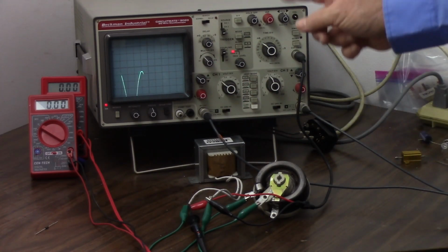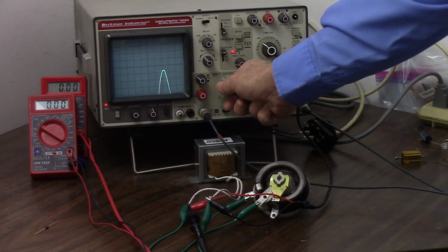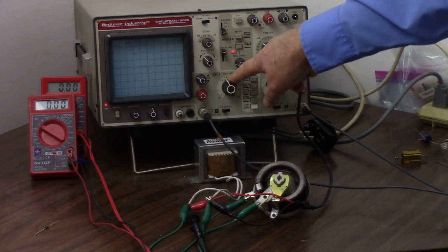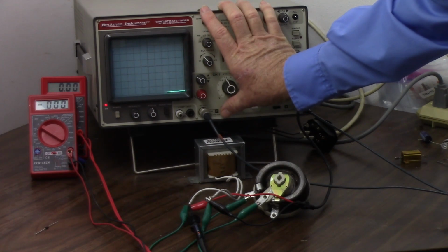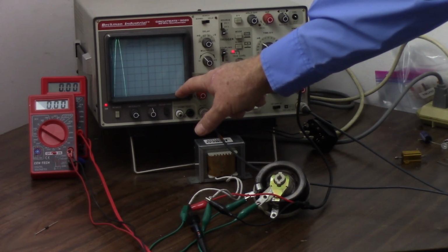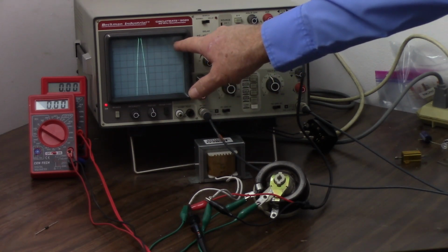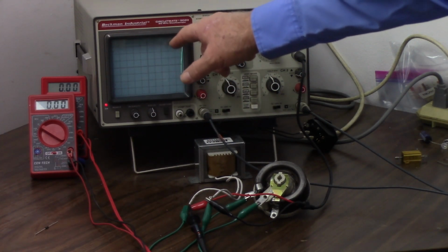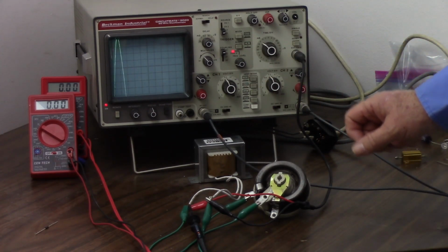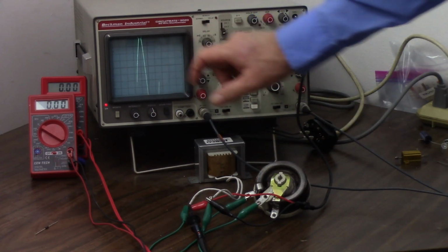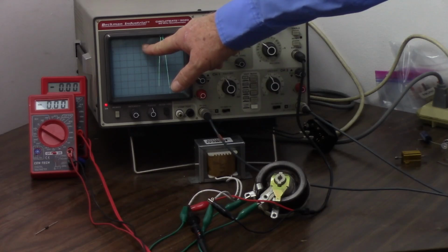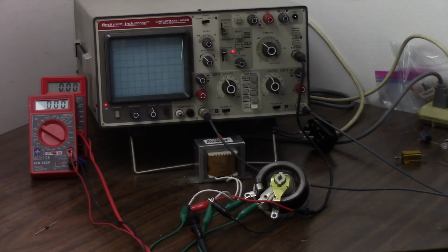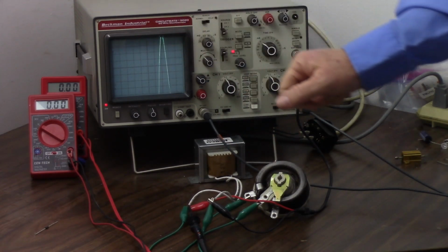Flip that up there, and I'm going to set this up at 0.2 volts per division times 10, so that's 2 volts per division. Let's double check our ground here. There we are. So 0 volts is at the bottom, so it's 2, 4, 6, 8, 10, 12, 14, 16 volts is kind of going a little bit off the scale to give us our 16 volts. So now what I need to do is start loading this down and watching that peak voltage. I know when the peak of my sine wave goes below 14 volts, that's when the output of my power supply is going to start dropping. So the question is, can I get 4 amps out of this transformer before that peak drops below 14 volts?